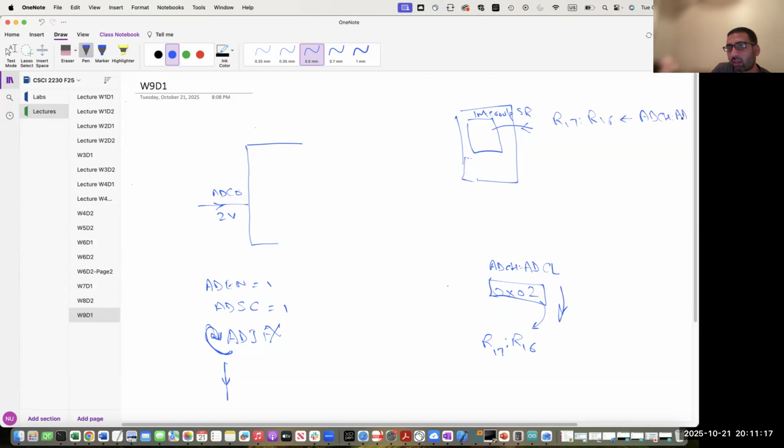and ADCL, right? But you have to first put this code in a particular location in memory, which is known as the address of the interrupt service routine for the ADC, right? So if you have written your program here, after that you will enable analog to digital conversion,